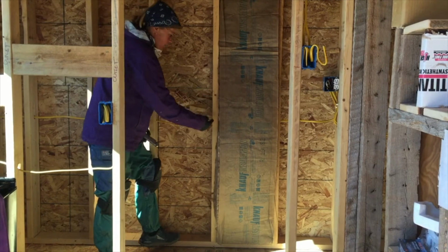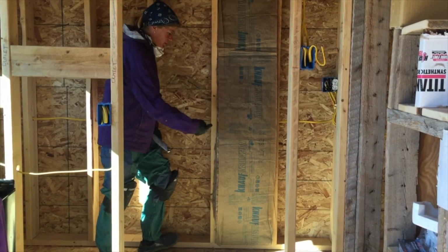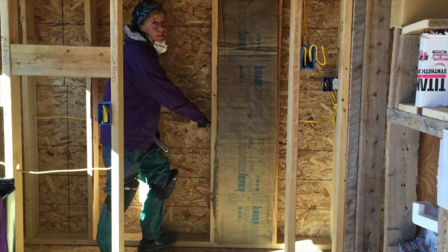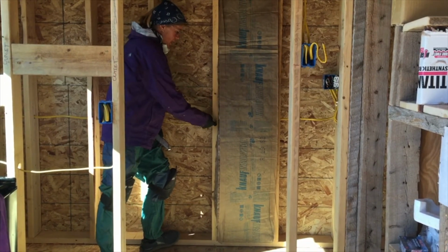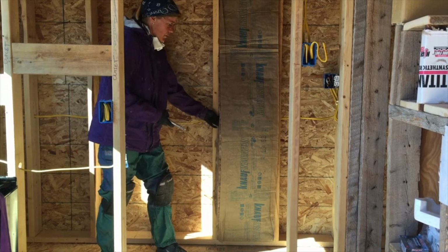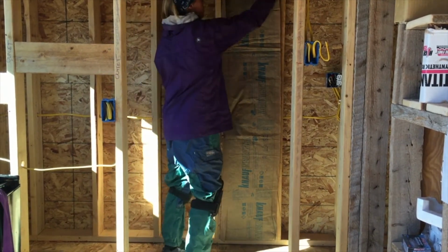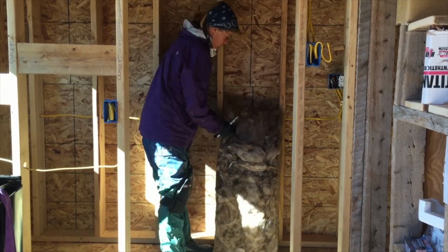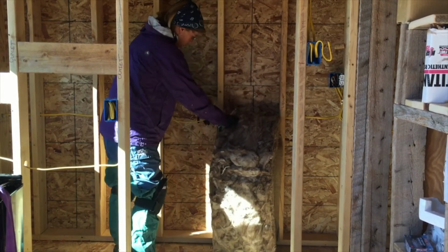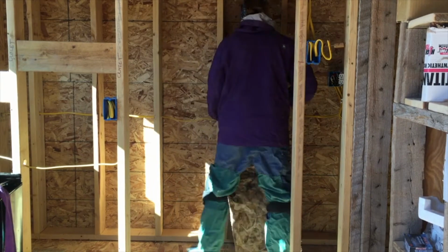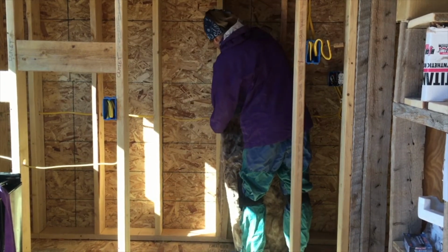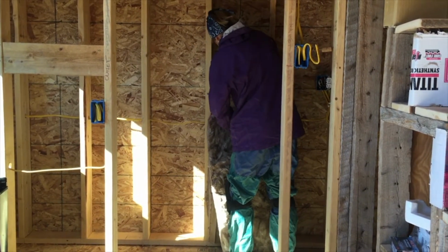That keeps us from, when we put drywall screws in, screwing so far we can hit our wires. Same thing on the outside when we're putting things through the sheeting. Ideally, we're in the middle. That also means we want to slit our insulation to the middle so that half of it can go behind and half of it can go in front. So I hold it up, I take my knife, I'm going to very carefully slit my insulation.